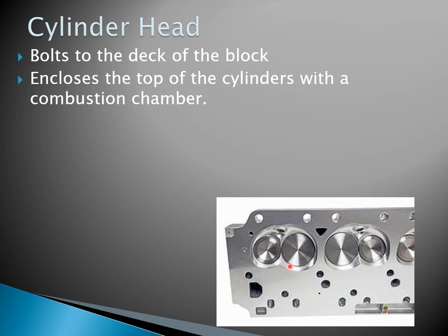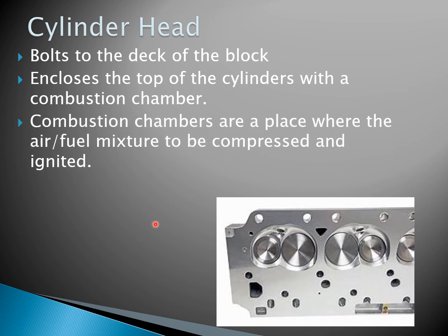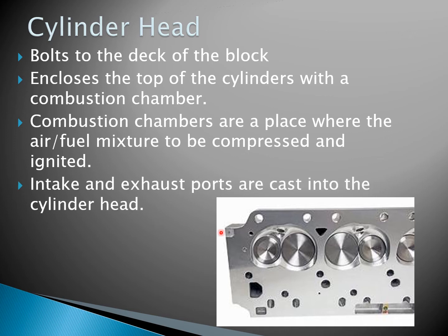Since I can't ask that question of you in person, I'm just going to have to give you the answer. And that answer is the intake valve is the larger one. So this would be intake valve, this would be exhaust valve, and so on down the line. And we'll talk a little bit more about that. This is where the air-fuel mixture gets compressed and ignited. The valves would actually be able to come out, but where they sit, the ports, is cast into the head itself. So there's a nice little green circle for you. Just remember this, when we talk about valves, the intake valve is the bigger of the two.